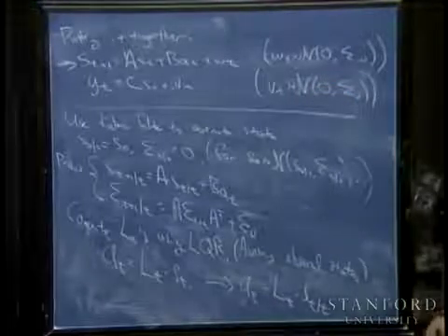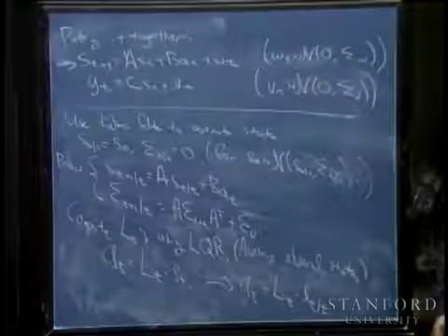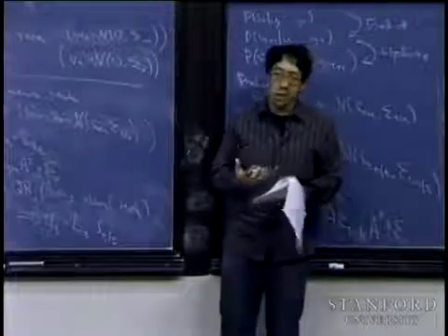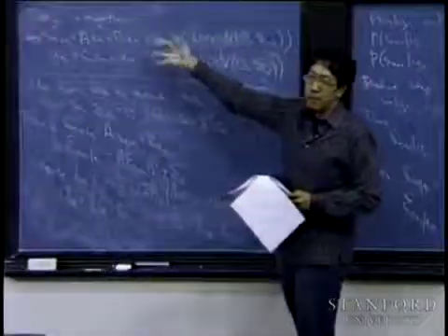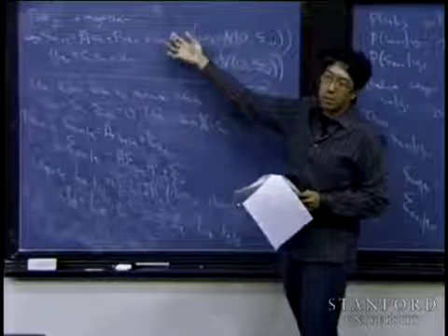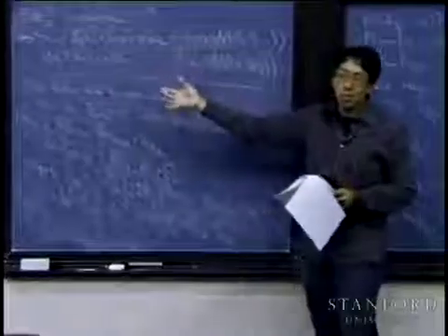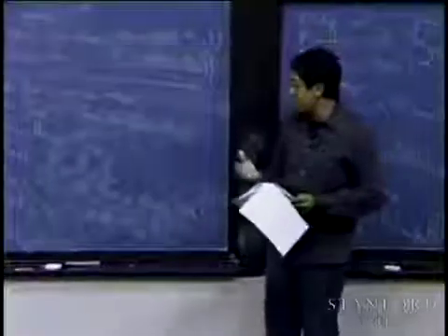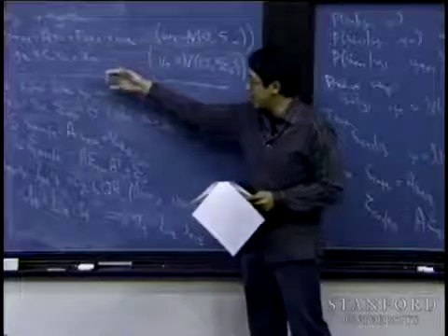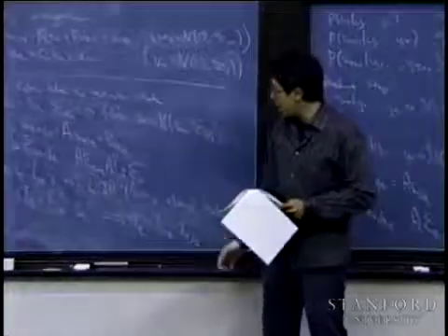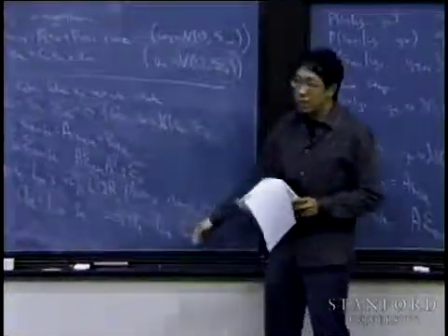And this is the intuition I gave earlier: in an LQR problem, it's almost as if the noise doesn't matter. In the pure LQR problem, the w_t terms don't matter. It's as if you could ignore the noise. It turns out that by elaborating that proof, which I'm not going to do, and you're welcome to prove for yourself at home, you can actually ignore the noise in your observations as well. s_{t|t} is your best estimate.